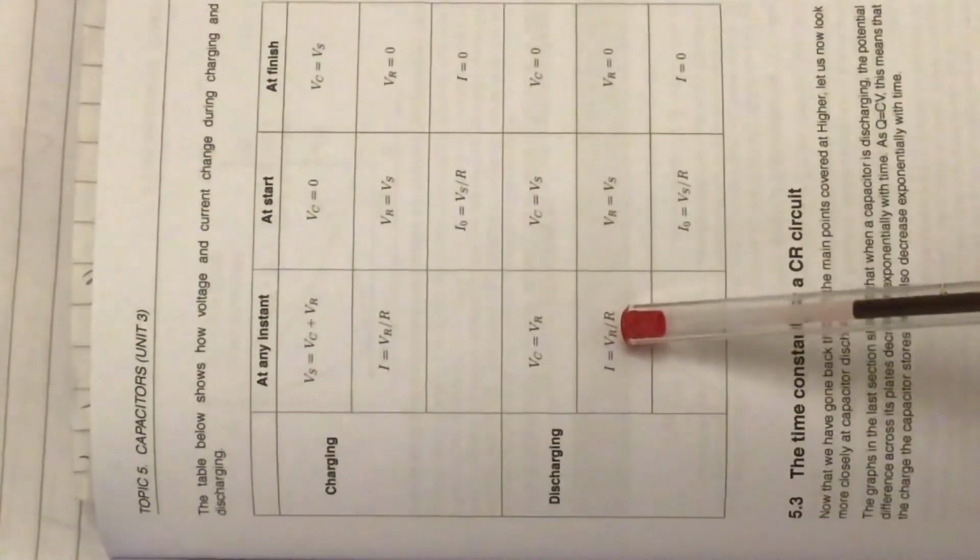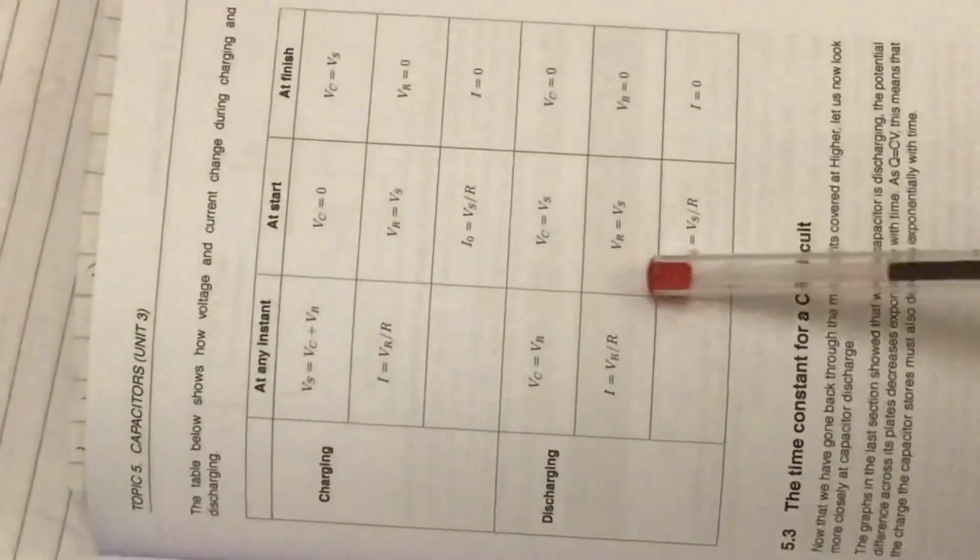So at any point in time, the voltage across the resistor, in this case the load resistance, would be maybe a bulb or some sort of device we want to run with the capacitor, or if you're just determined to do something silly, perhaps a bit of wire that you're trying to melt with the capacitor. And there we go. So initially, the voltage across whatever it is we're going to use as our load equals the supply voltage. But remember, the supply voltage is the capacitor voltage when we start to discharge something. The voltage across the resistance ends up being 0 when we're finished. Current, Vs over R to begin with, 0 to end up with.